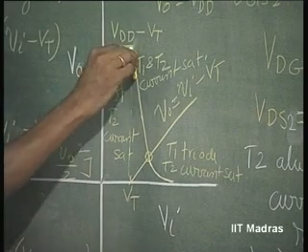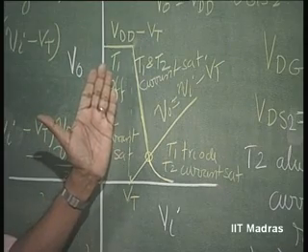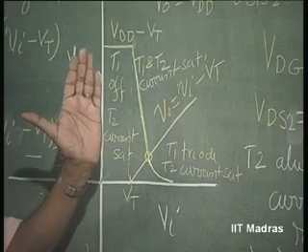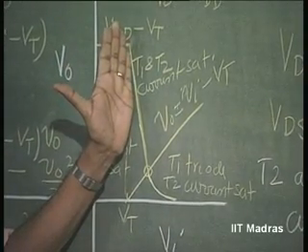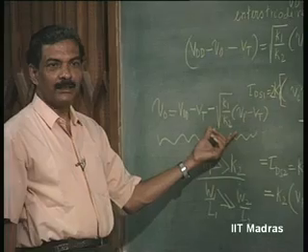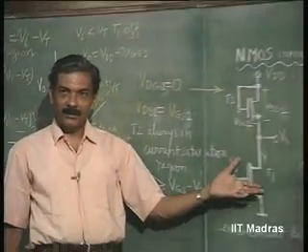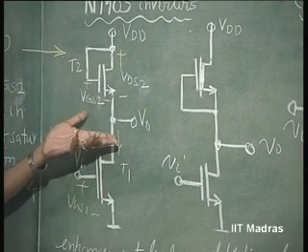So, you can use this as an amplifier, and that is beautiful, because you are using a nonlinear load and the transfer characteristic becomes perfectly linear, and the gain is root of what? K1 by K2. So, if you use it as an amplifier, for example, in an NMOS operational amplifier, the gain is straight away known as root of K1 by K2.